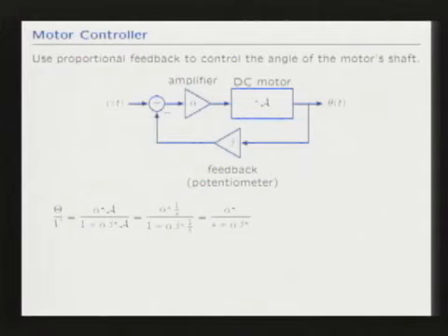And then I put it into this thing, which is really just a 741 wired up like I showed in the first example, so that it takes the difference between two things, the desired input, which is a potentiometer that I'm turning here, and the actual position, which is the potentiometer up here, the same kind of potentiometer, just one that I turn, the other the motor turns. The op-amp figures out the difference, multiplies it by a gain alpha, and presents it to the motor.